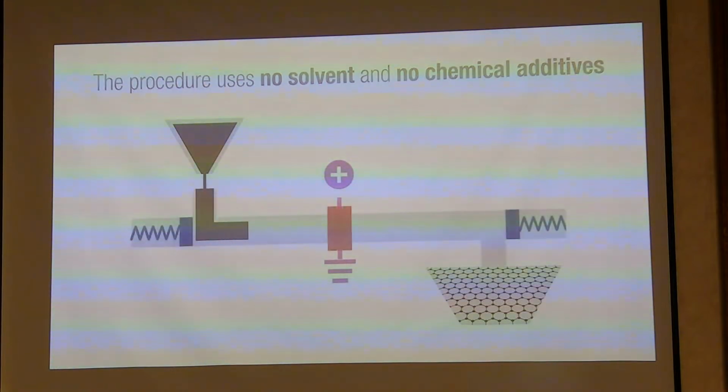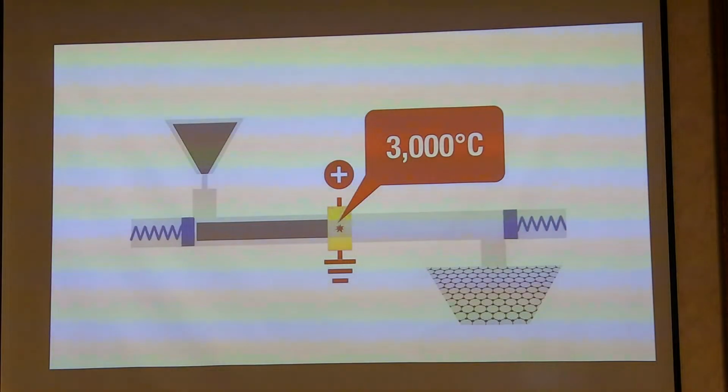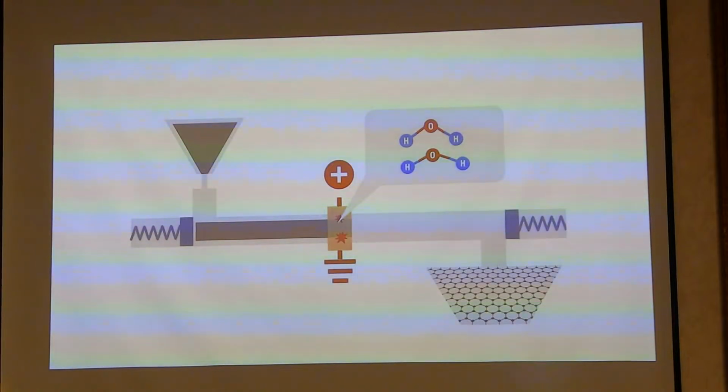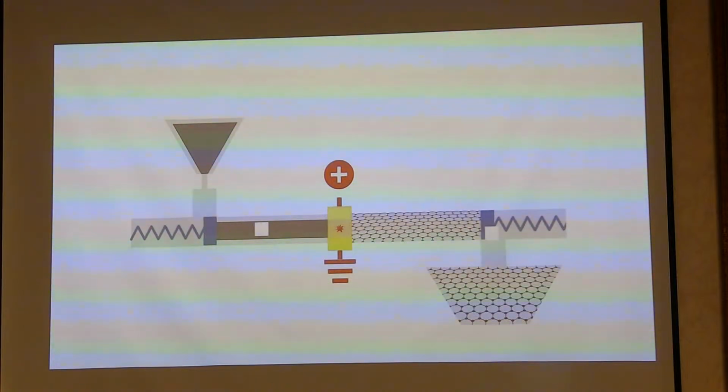By placing any solid carbon material between two electrodes and applying 200 volts in a short electrical pulse, the temperature instantaneously heats to almost 3000 degrees centigrade, and every chemical bond in the material breaks. The non-carbon elements sublime out, and the remaining carbon atoms reconstruct into graphene, all in a bright flash of light in less than 1 second. The flash process happens so fast that the surrounding container does not even get hot.